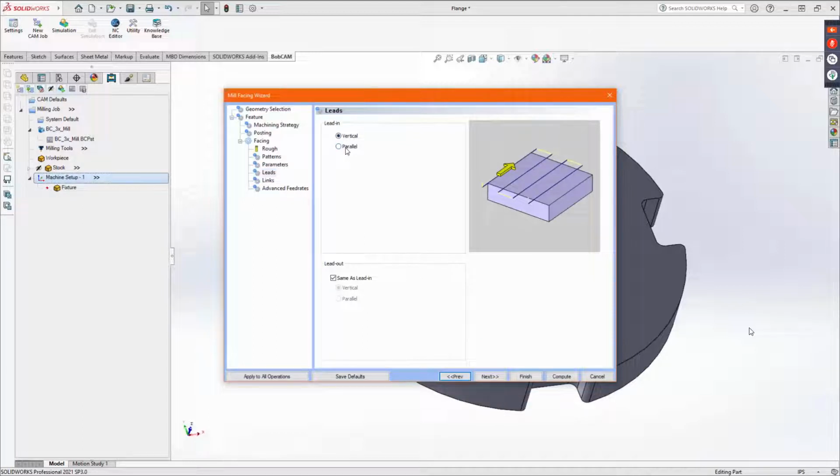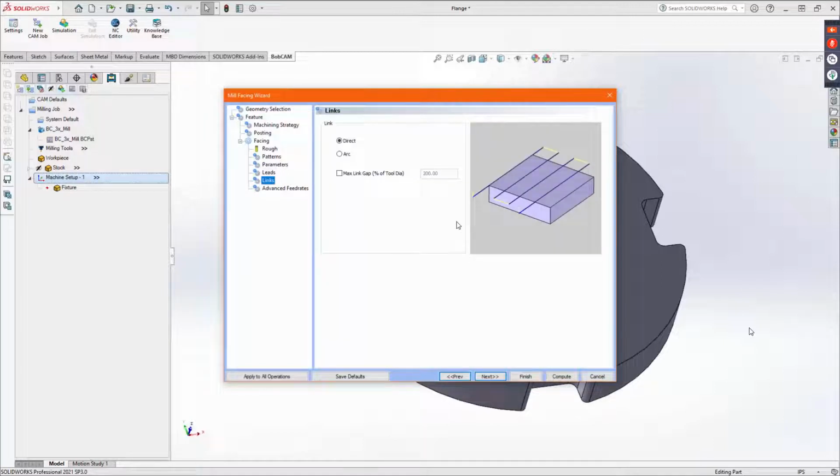I don't feel like I need an additional lead, but you can always add an additional lead in that's going to be extra on top of the off workpiece or on workpiece value. So especially if you're doing on workpiece at 50%, you would want to put in a length here to start off the part to move into it. Because typically those cutters are only side cutting in mills or shell mills or fly cutters.